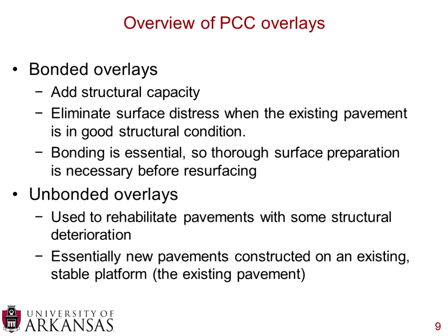It is essential to have bonding, just like asphalt concrete overlays. If you do not hold and maintain that bond, you will not be able to get the full benefit of that added structural capacity. And we'll see that in the upcoming slides about how these loads are actually transferred down through the pavement structure.